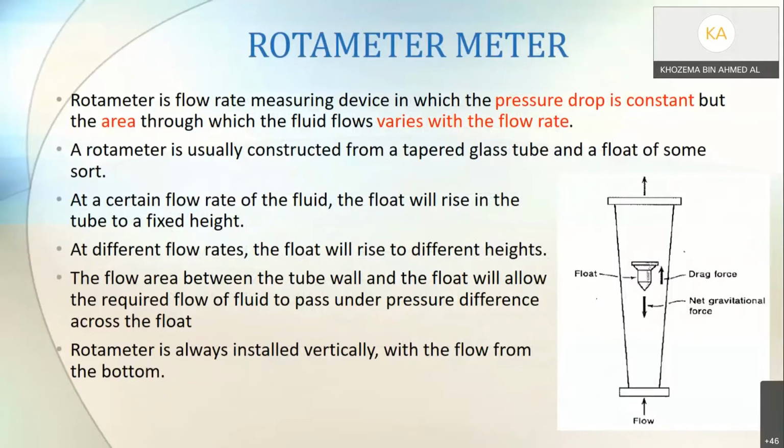So far we have looked at the venturimeter and orifice meter, where the main mechanism to measure the velocity change, the flow rate, the mass flow rate, is by the difference in pressure, right? So you have point A and point B, and you mount a manometer, and based on the pressure difference, you can use the equation to find the value of velocity, and you can find the value of flow rate. So the main idea, if you see here, is that we want to measure our flow.